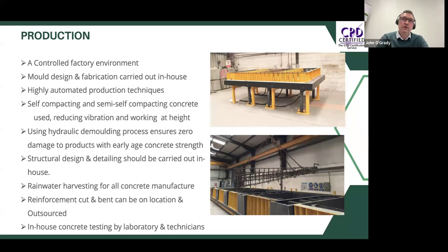And then once you're into production, it's important to track the quality. So having an in-house lab and testing technicians who are taking cubes basically every day, but there's I think a 24-hour, 7-day, and a 28-day. Those are the key ones that we would follow.